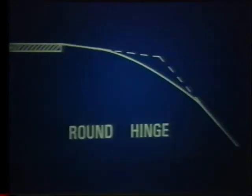Ideal slopes alongside roadways are about a 10-to-1 or flatter between the travel lane and the hinge point. On the other hand, vehicles will become airborne at about 40 miles per hour as they cross hinge points that are 6-to-1 or steeper. Most front slopes forming a ditch are 6-to-1 or steeper. Rounding the hinge point will greatly reduce the tendency to become airborne. Drivers have more time to regain steering control with the increased roundness.